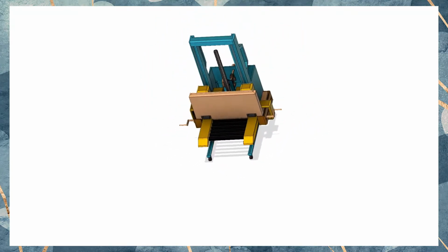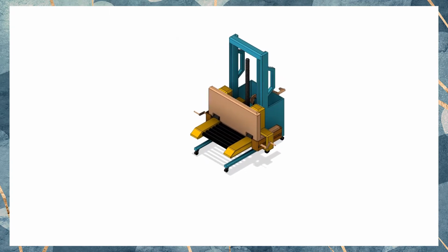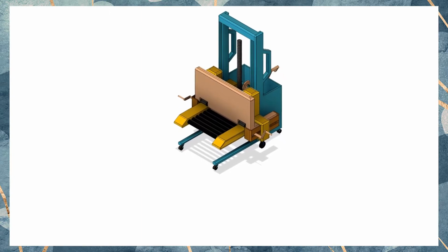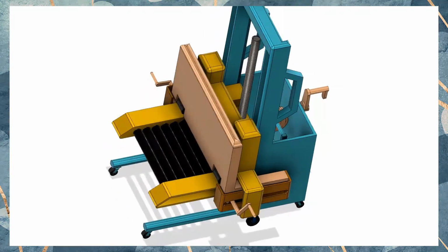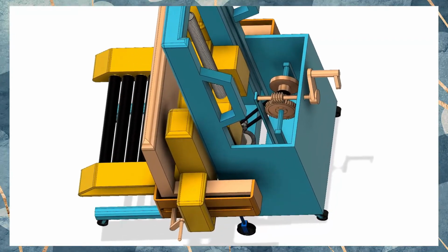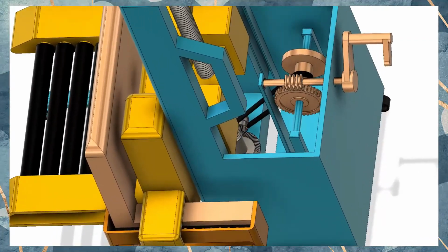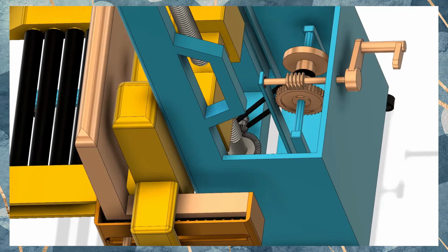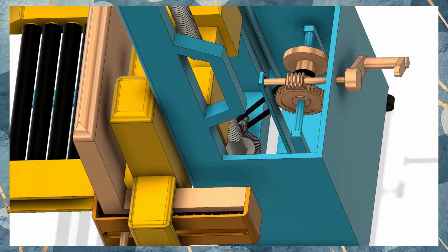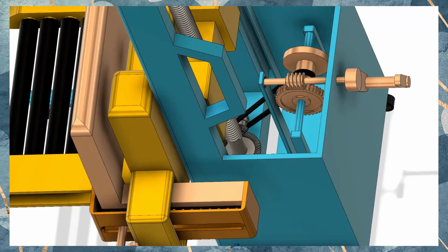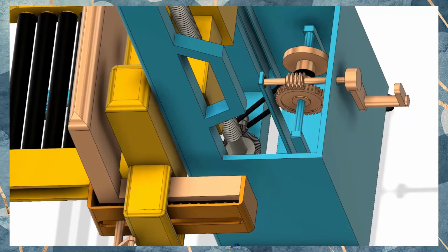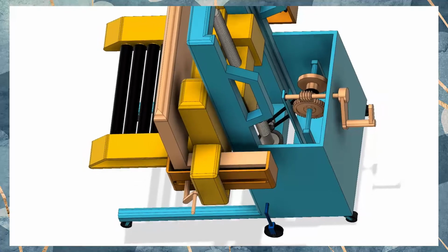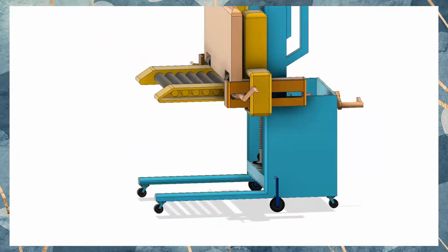For the vertical movement, we use the worm and gear mechanism as well as the bevel gear mechanism. By rotating the winch handle, it will produce the rotating movement of the worm and gear mechanism. This will lead to the rotation of the belting, which is connected to the shaft of the worm gear to the bevel gear. The bevel gear will rotate the threaded rod, thus moving the threaded plate upward. The forklift that is connected to the threaded plate will move accordingly with the bevel gear rotation.